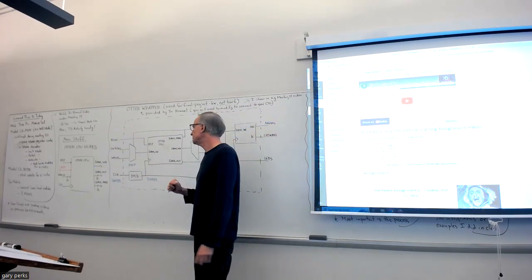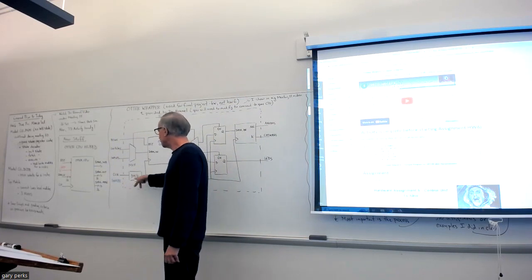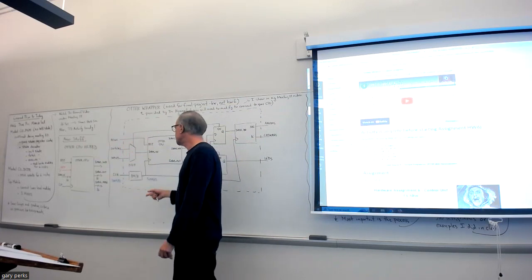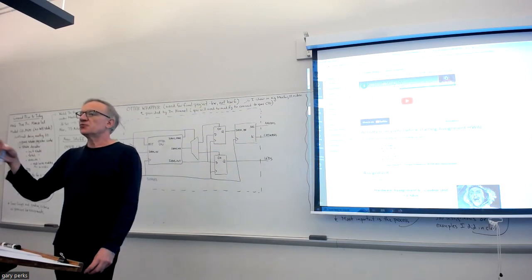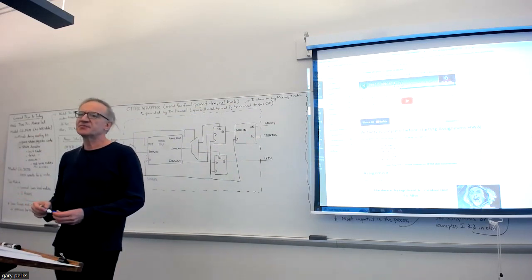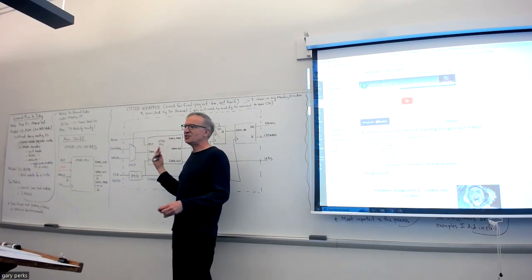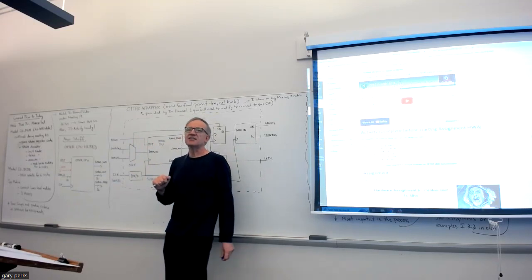this other circuitry that you see over here that's sequential. Now, I think I mentioned this before, but I'll say it again. The reason we're dividing the Basys 3 board clock frequency down to 50 megahertz is just to get some wiggle room in your design. By slowing down the clock, if your CPU isn't super efficient, it still should be okay.